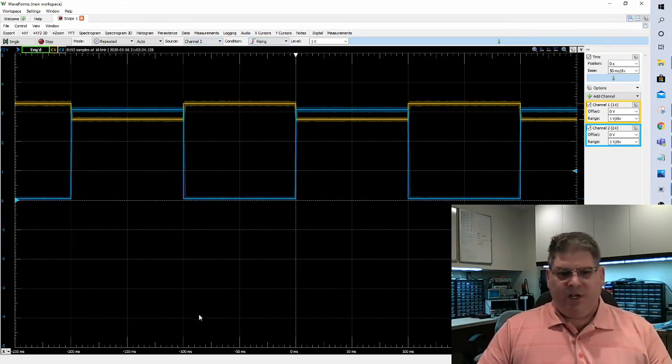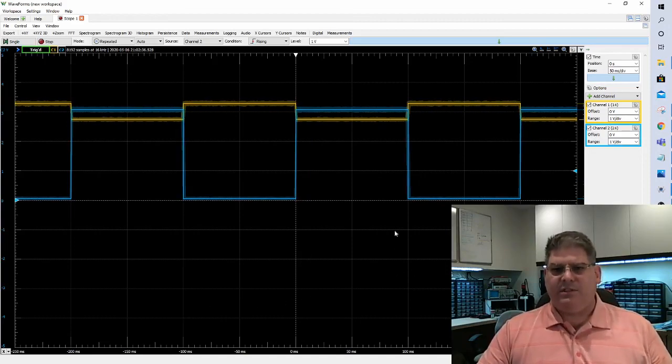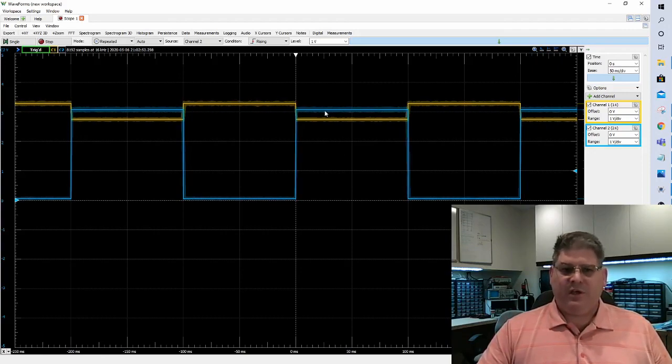So what we're seeing is 100 milliseconds on, 100 milliseconds off, and our volts per division is set to 1. So 1, 2, 3, and a little bit to here. You'll notice that it's a little bit low, and that's due to internal resistance in the microprocessor. There's actually a small voltage drop across the FET, and this way we're looking at just the voltage drop across the transistor, so we won't worry about that too much.